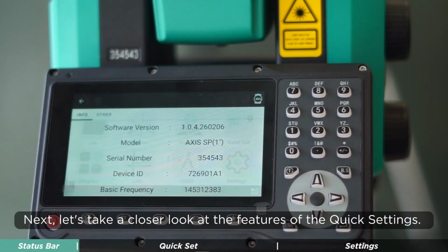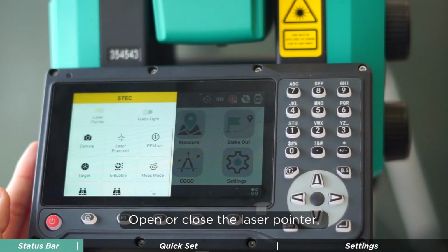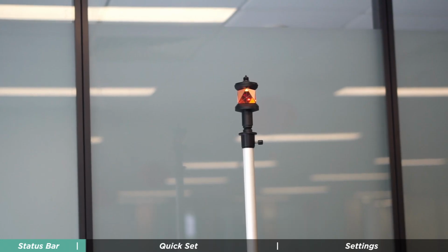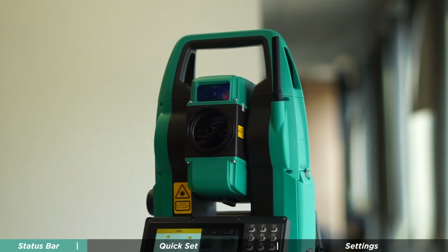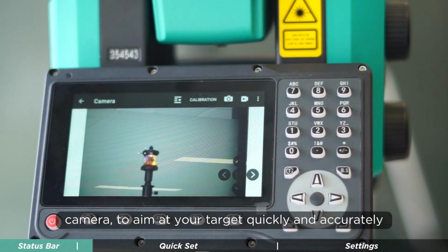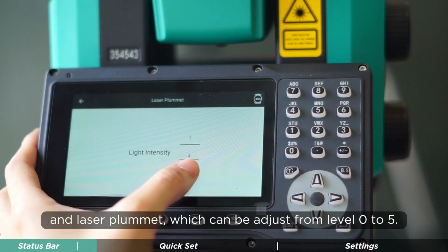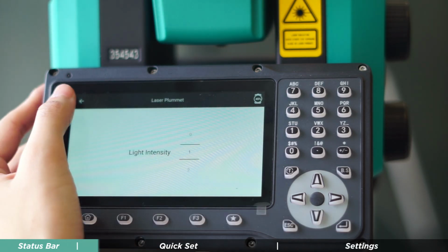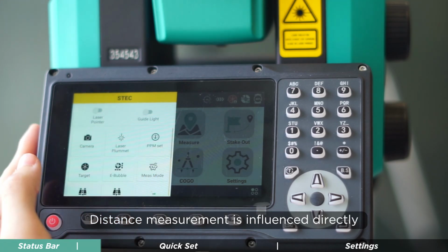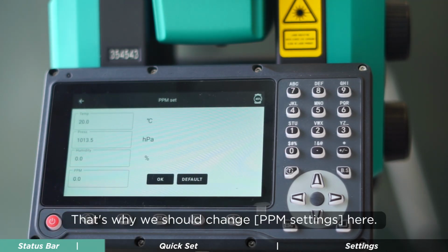Next, let's take a closer look at the features of the quick settings. Open or close the laser pointer, guide light, and camera, to aim at your target quickly and accurately. And laser plummet, which can be adjusted from level 0 to 5. Distance measurement is influenced directly by atmospheric conditions. That's why we should change ppm settings here.